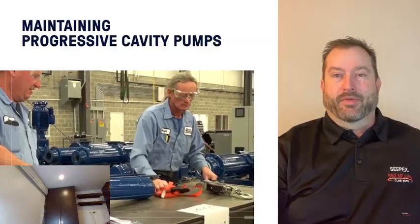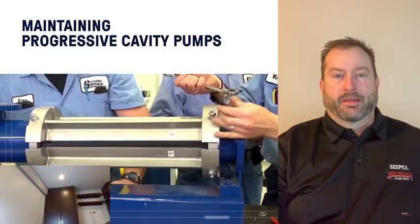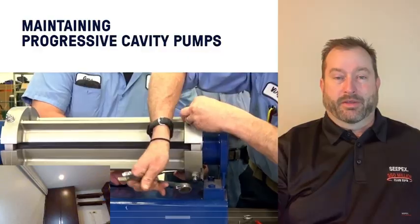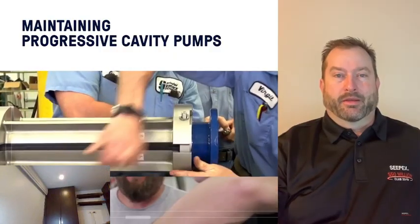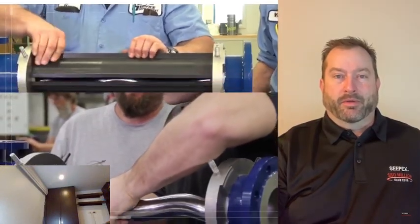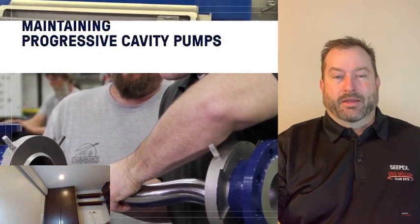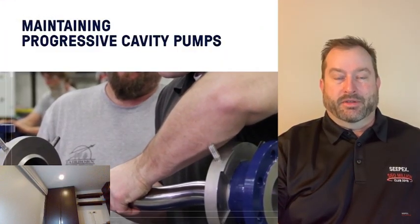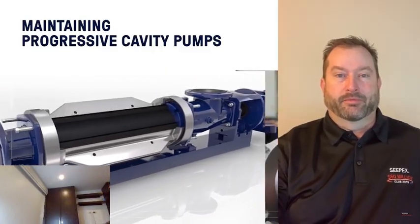Many PC pump manufacturers now have a type of maintain in place component to their pumps, and this means you can actually go in, change the stator, sometimes the rotor or other components, without having to remove any piping whatsoever. That seems to be pretty common among most of the major manufacturers now. The maintain in place actually speeds up the maintenance time. So to change the stator, the times to do that are greatly reduced compared to a conventional stator.